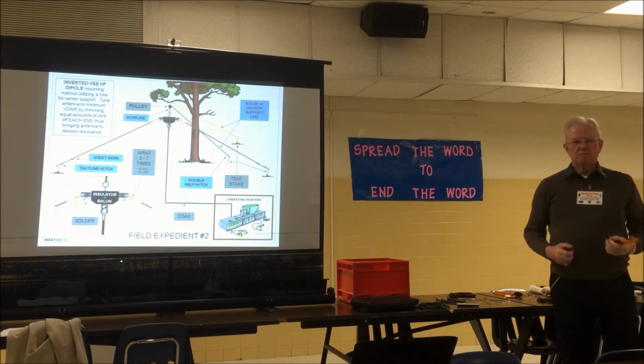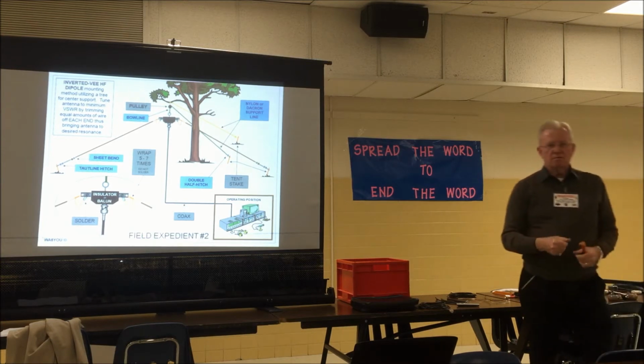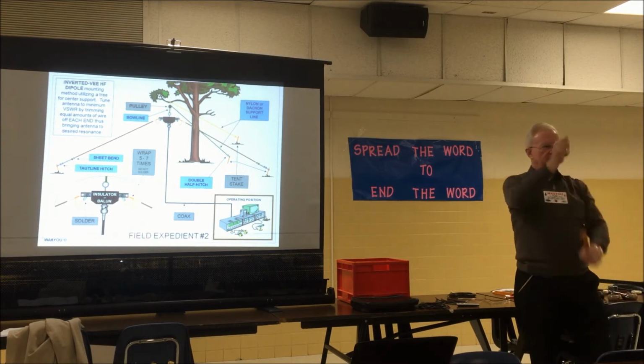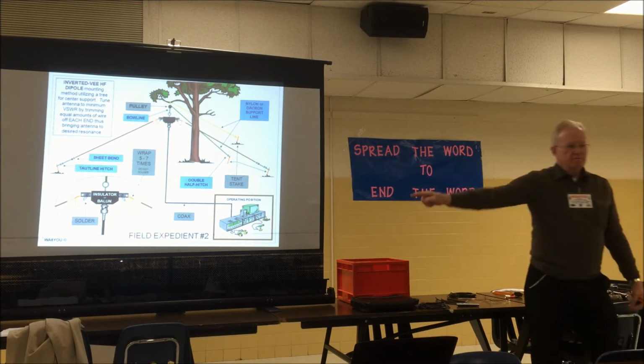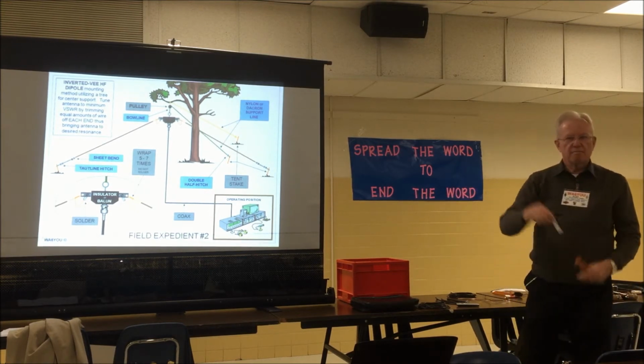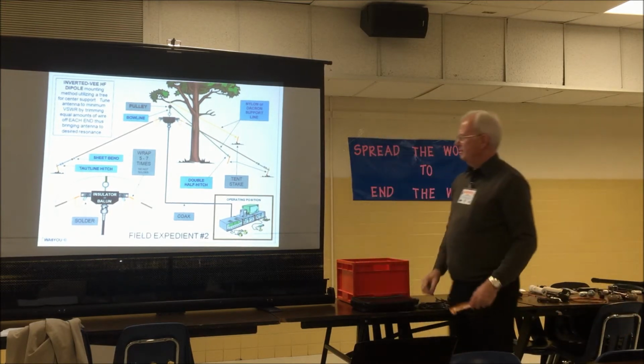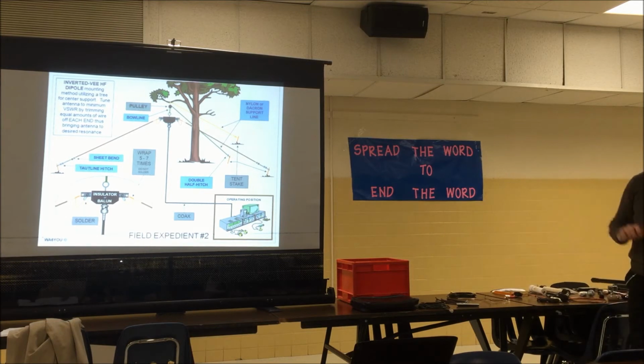Antennas on it. Anytime I want, hurricane's coming, ice storm's coming, I lower that sucker, put it right on the grass. Wait till it passes, the next morning I go out, raise it back up. This is a must. Notice on the ends of this Field Expedient antenna, no insulators.